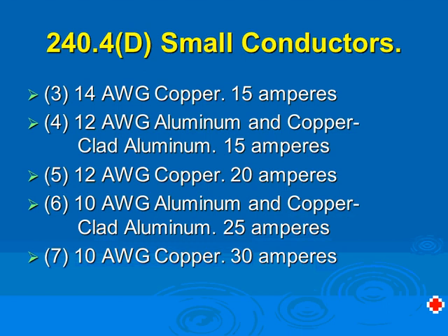It's not all of them. I mean, typically your lighting circuit is 20 amp in a commercial building. Your receptacle circuit is 20 amp. 20 amp is number 12, and you might go for a lighting circuit of 30 amp and pull number 10 into the boxes and tap with number 12 to the other lights. We do that sometimes. So that's about it.